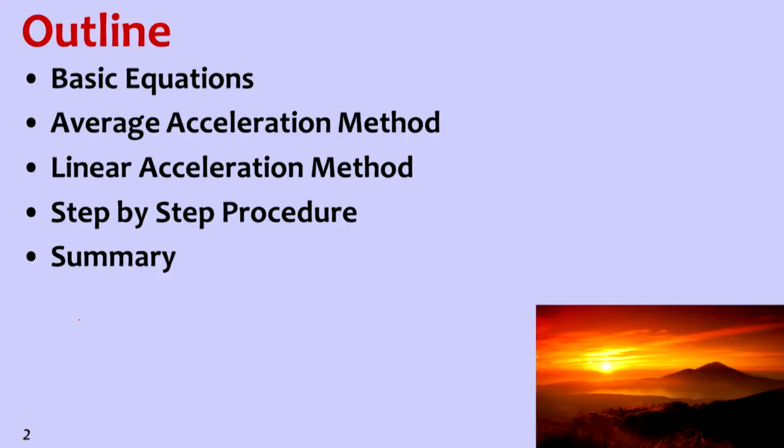In Newmark's method, the forcing function, which is in the form of acceleration or force, we will calculate in between two time instants, either as a linear variation between the two time instants or as an average variation between the two time instants. So those two topics we will discuss in this class.